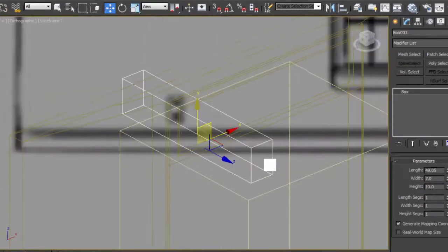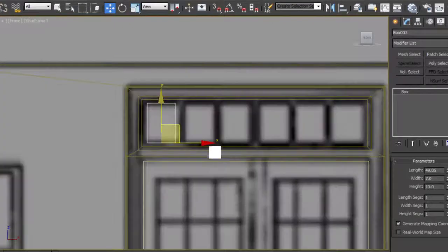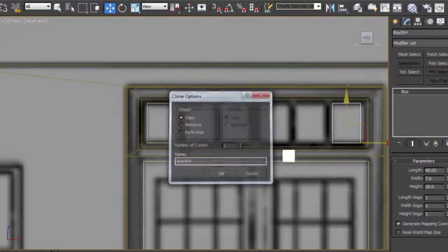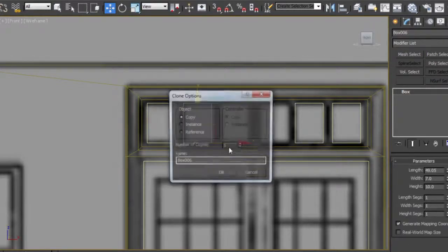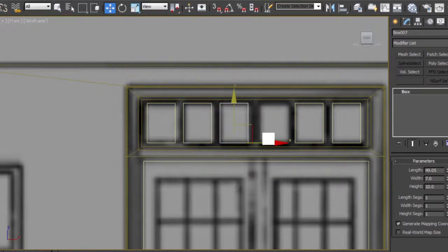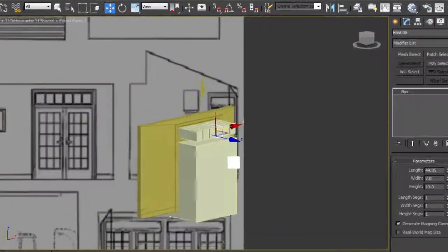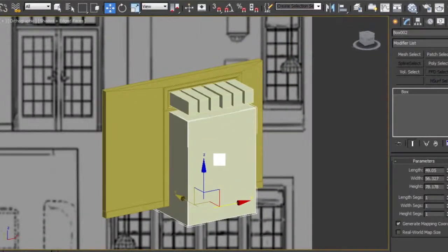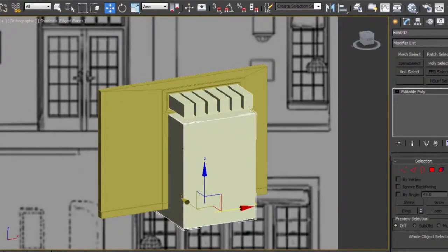Pretty good. It's intersecting, so it will create a good Boolean. I will now duplicate one at the opposite end. Work my way to the middle, trying to space them evenly. Of course, I could use an array to get an exact spacing that's even. In this case, I'm okay winging it a little bit. That looks relatively even. And remember that for Booleans, you always get better results if you can manage to have as few Booleans as possible.